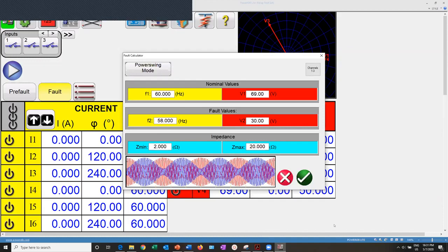All right, thanks. Actually, we do have one more question I think we should answer. It's going to be for Abel. In your experience, if there are 2 lines back to back, will zone 2 of line 1 operate first, or zone 1 of line 2? Similarly, will zone 3 of line 1 operate first, or zone 2 of line 2?